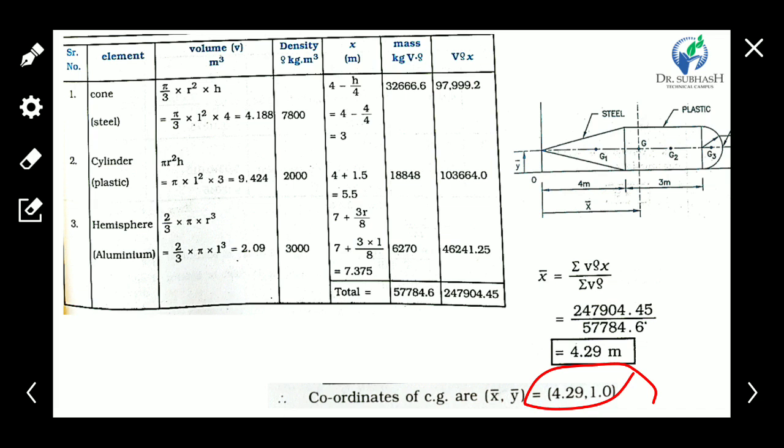Again I repeat that for a solid, to find the center of gravity we consider the mass. For a lamina type or plane type object we consider the area, not the thickness of the lamina or plane. For wire type elements we only consider the length of the wire, not the diameter or thickness or section of the wire. So in a solid we consider the mass.